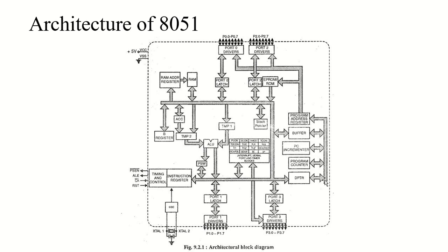Also it serves as a base register in case of indirect jump instruction handling, lookup tables, and external data transfers as well. And just like the program counter, the data pointer also does not have a single internal address. DPL and DPH are each assigned an address, right?